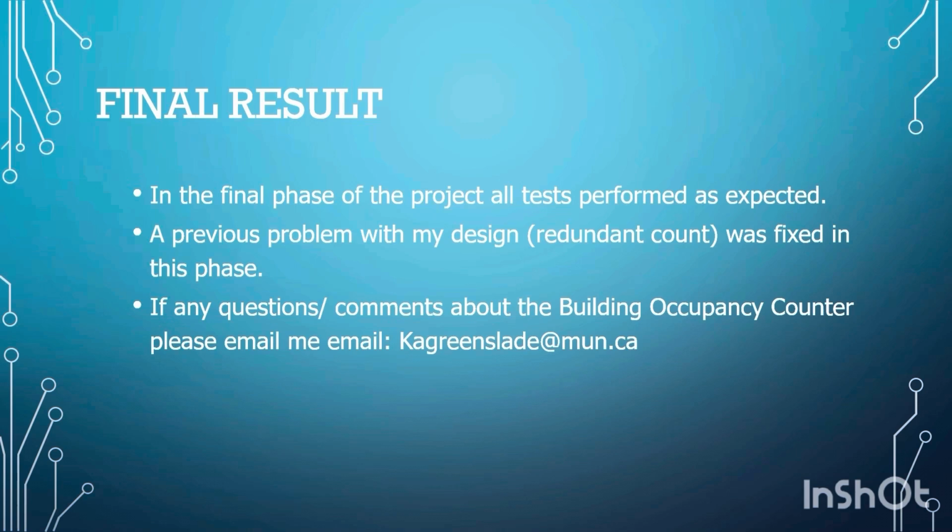And this is an issue I was having trouble with, but to fix this issue, I added some logic to my Arduino code, basically some timers, like enough time for me to walk by both sensors. When sensor A is triggered first, or sensor B, the other sensor wouldn't be triggered, like picking up in that time frame.